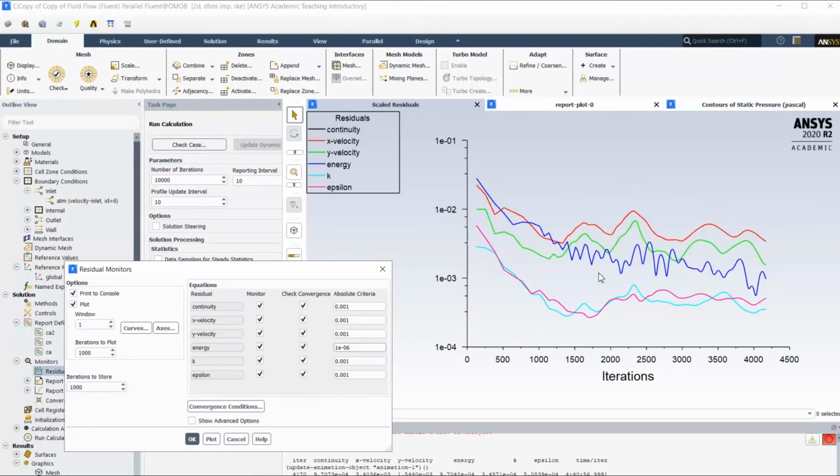But these small perturbations basically do not influence the formation of the flow and flow characteristics, yet this kind of oscillation stays constant at a quite high value, like 10 to the minus 2 for the residuals, so they will never drop. They cannot drop for two reasons.